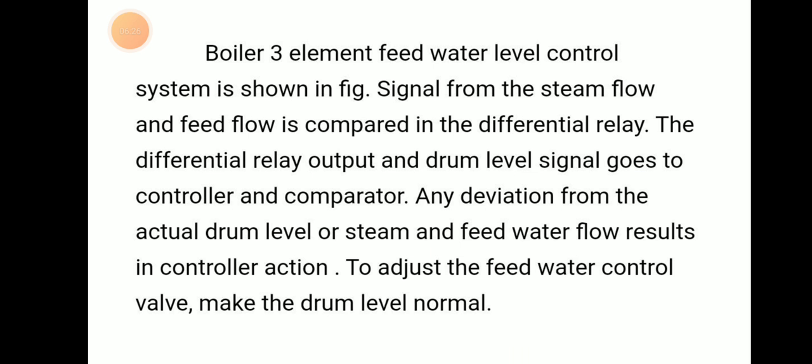The boiler 3-element feed water control system is shown here. The signals from the steam flow and feed flow are combined in the differential relay. The differential relay output and drum level signal go to the controller and comparator. Any deviation in the actual drum level or steam and feed flow results in control action, to adjust the feed water control valve and make the drum level normal.